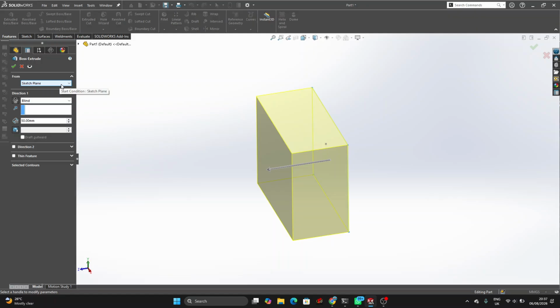So I can decide not to extrude it from there, and I can extrude it using an offset. Initially it is 0 millimeter. What offset does is it moves something away from the initial position. If you are offsetting by 0 millimeter, it's still in the initial position. So nothing is changing. So we are going to offset it by 10 millimeter now.